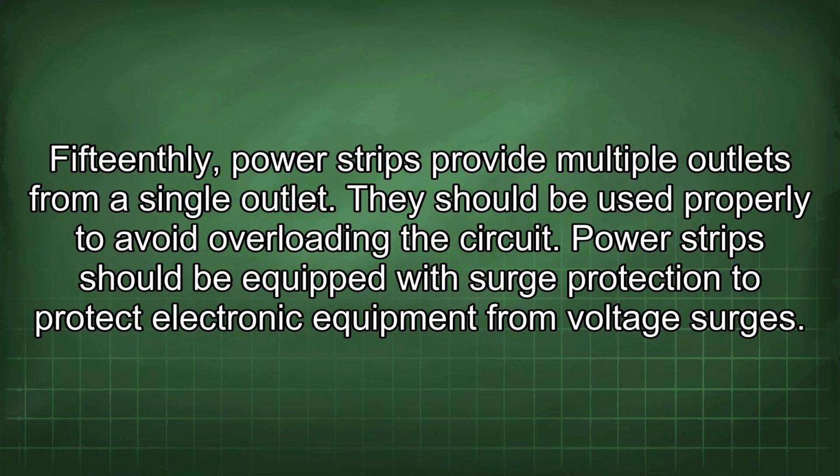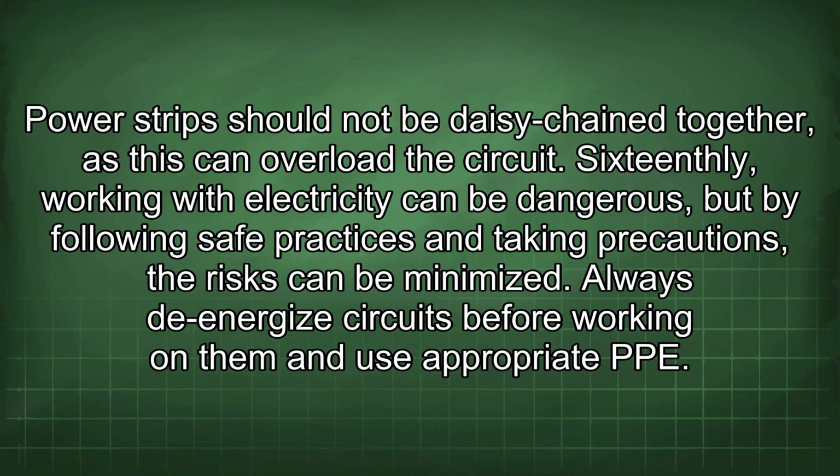Fifteenth, power strips provide multiple outlets from a single outlet. They should be used properly to avoid overloading the circuit. Power strips should be equipped with surge protection to protect electronic equipment from voltage surges. Power strips should not be daisy-chained together, as this can overload the circuit.